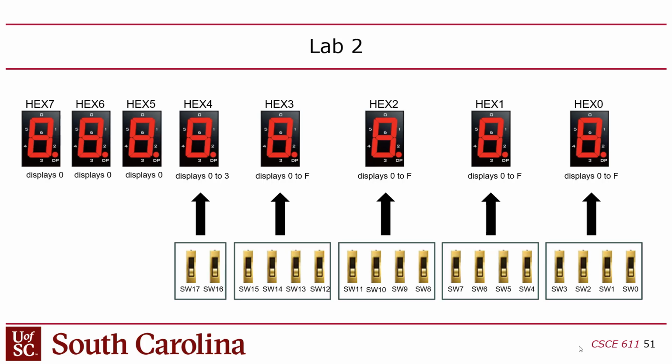So generally, when you have a 7-segment display, only one of them is actually driven at a time, and then they're scanned really fast. It uses the persistence of vision of the human eye to make it look like they're all lit up when in reality only one is lit up at a time. But on this FPGA board, they actually have 56 bits driving all 8 of these hex displays. They're all being driven all the time.